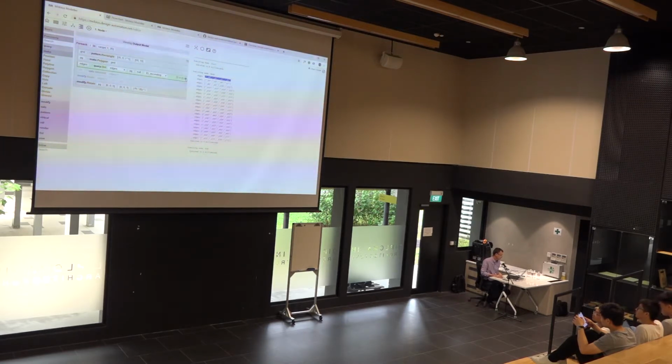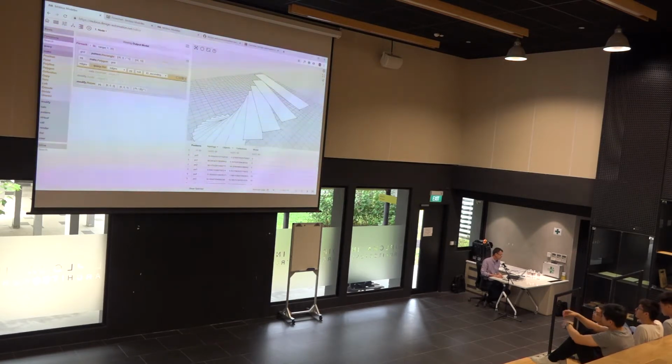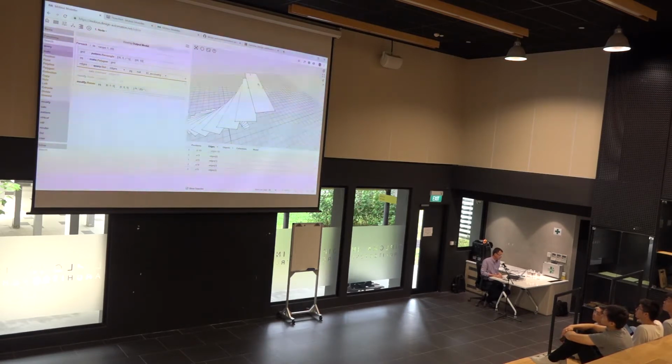Instead of printing, you can click this other button here, which is show geometric entities, and when I click that one, it will actually show me that there's 4 edges, 0, 1, 2, 3. So when I look at my edges here, I can see 0, 1, 2, 3, edge 0 is E72, edge 1 is E73, so I can actually see how the edges are numbered.